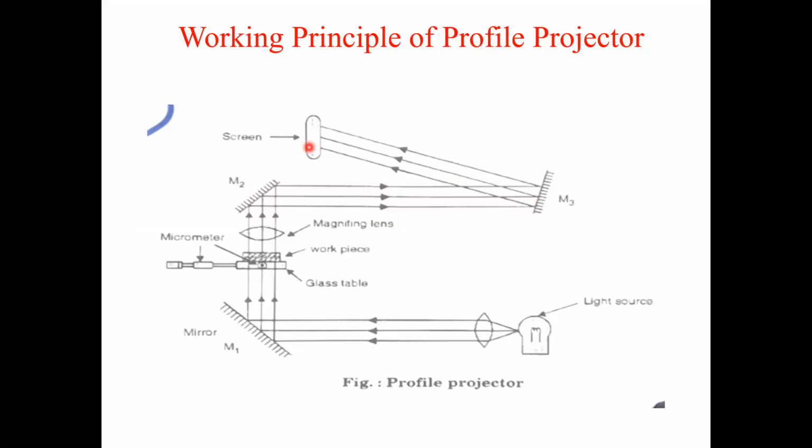That means if you observe the screw, you cannot directly measure the pitch, the major diameter, the minor diameter, or the thread angle. Therefore, the image of that screw is magnified a number of times, and with the help of the magnified image, you can measure the different features, like major diameter, minor diameter, pitch, thread angle, depth, all the parameters.